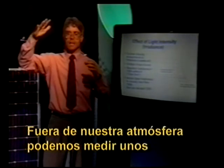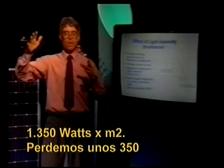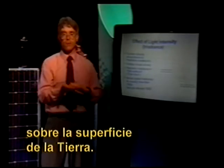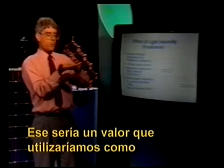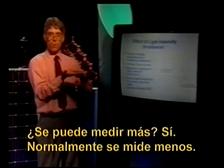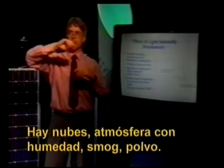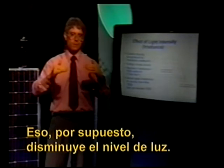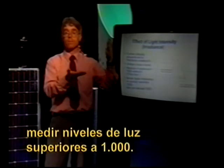Outside of our atmosphere, we can actually measure 1,350 or so watts per square meter. We lose about 350 going through the atmosphere. We're left with about 1,000 at noon on the Earth's surface. That would be a value that we would use as a standard measure, 1,000 watts per square meter. Can you measure more? Yes. Typically you measure less. Clouds come by, there might be atmospheric moisture, smog, dust, cloudy days. That's going to lower your light level, of course. But there are conditions under which you can measure light levels greater than 1,000.